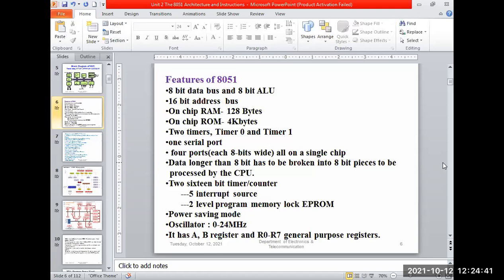Now, how are the above 3 ohm and below 3 ohm connected? Yes. This 3 ohm and this below 3 ohm are both connected in series. So 3 plus 3, what will it be? 6 ohm. Now the circuit looks like this: this branch totals 6 ohm and this branch totals 12 ohm. Now, how are 12 and 6 connected? Yes, so you have to find the parallel combination of 12 and 6.